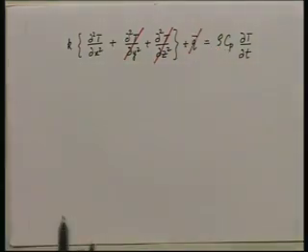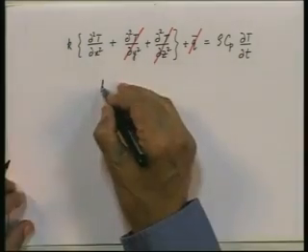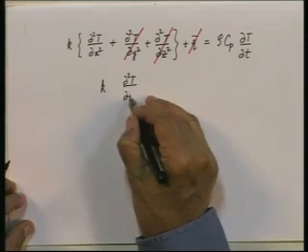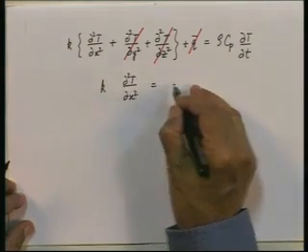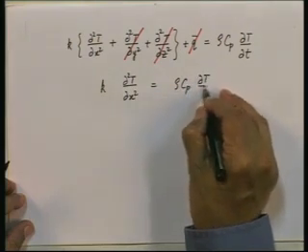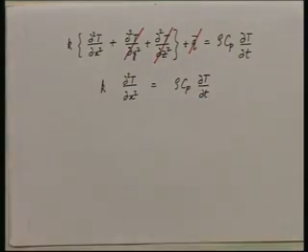So, in this particular case, the differential equation will reduce to the form k d2T/dx squared is equal to rho Cp dT/dt. That is our differential equation in this case. Rho k into d2T/dx squared is equal to rho Cp dT/dt.